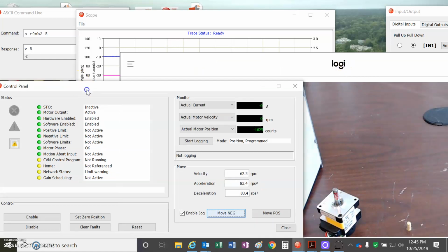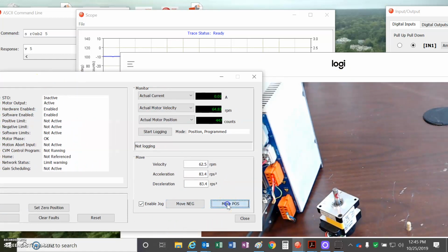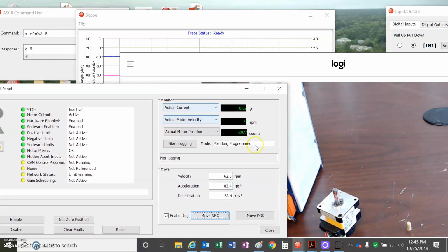And again, just be very careful of what happens when you lose your encoder, right? You disconnect the encoder, you get false counts, you get count drifts, you can monitor the position here, and you'll see your phase will start to leak. Your current will go way up.